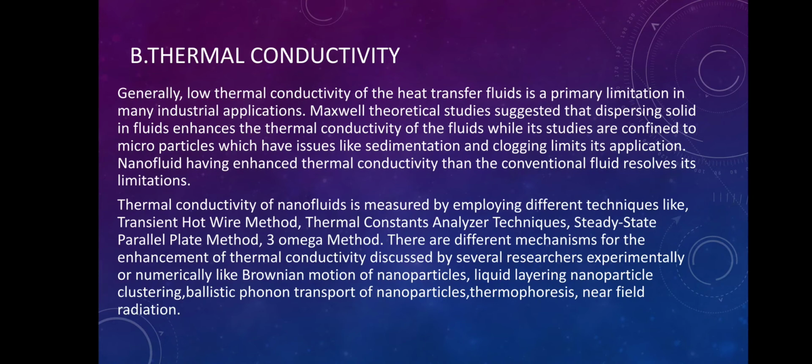Thermal conductivity of nanofluids is measured by employing different techniques like the transient hot wire method, thermal constant analyzer technique, steady state parallel plate method, and 3 omega method. There are different mechanisms for the enhancement of thermal conductivity discussed by several researchers, experimentally or numerically, like Brownian motion of nanoparticles, liquid layering, nanoparticle clustering, ballistic phonon transport of nanoparticles, thermophoresis, and near field radiation.